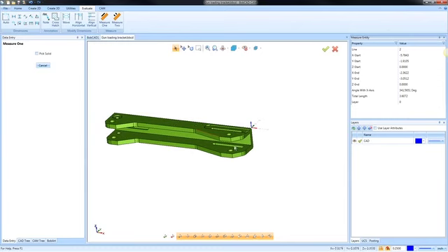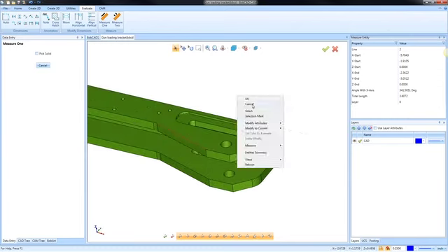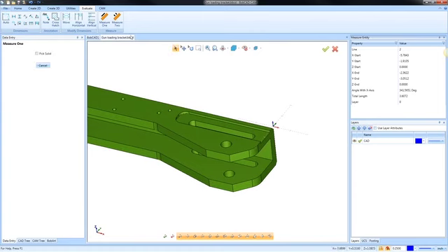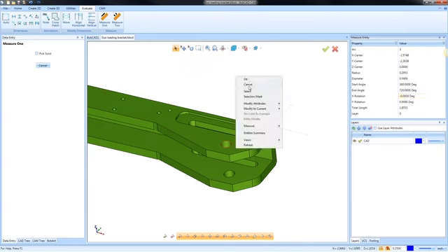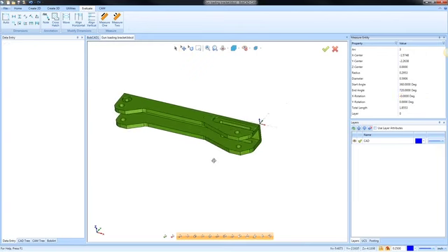So you don't need to do that now. You can just measure right off the model, and we can do measure 1, and we can even pick up the radius size here. We can pick on the edge of this hole here, and you can see how we're able to measure that as well. Okay, so just a little tip there, but all right, so we measured the part.